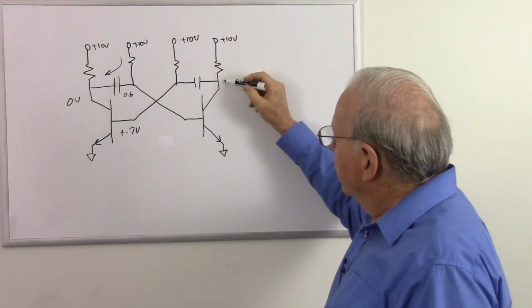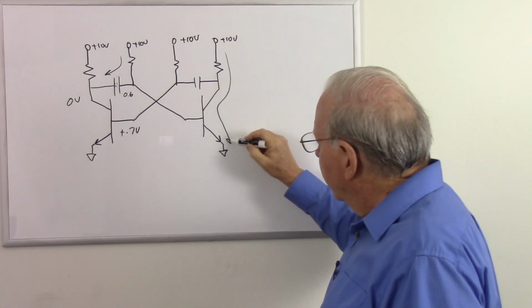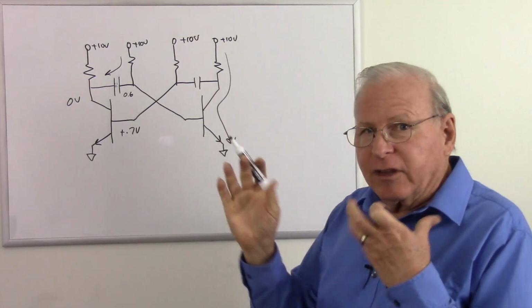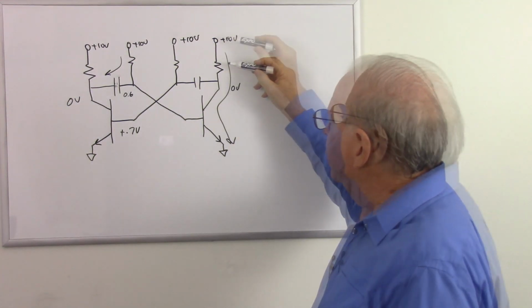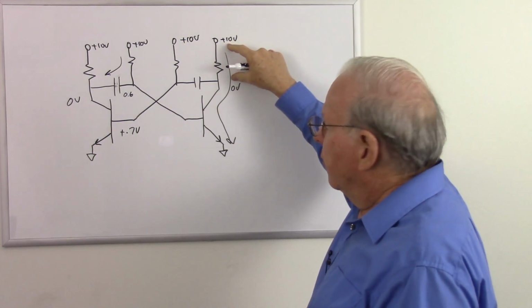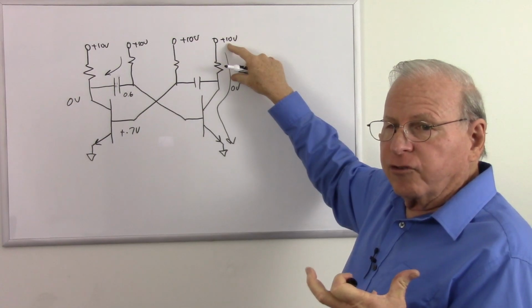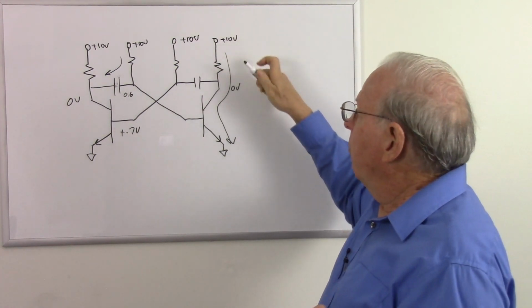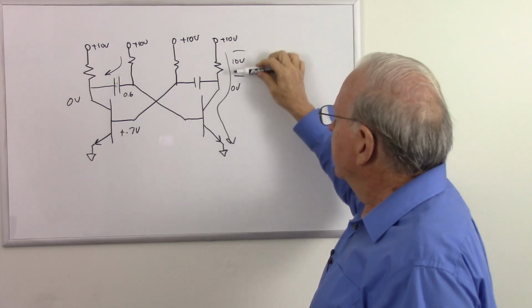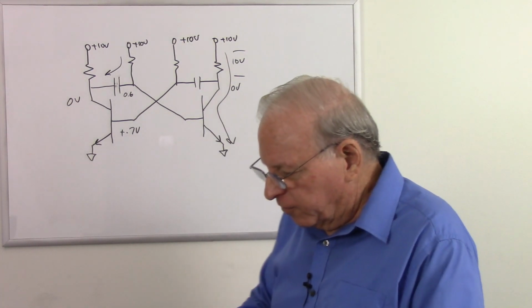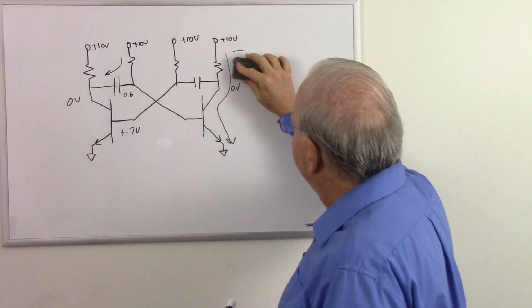So we're going to get a lot of current flowing through this transistor. And because it looks like a closed switch, for two reasons, we'll see 0 volts here. The other one is, if we have enough current, this resistor is going to cause a voltage drop. The more current, the more voltage. Well, when we get to 10 volts across there, start with 10, lose 10, we have 0 left over. So two ways to look at why that has 0 volts.